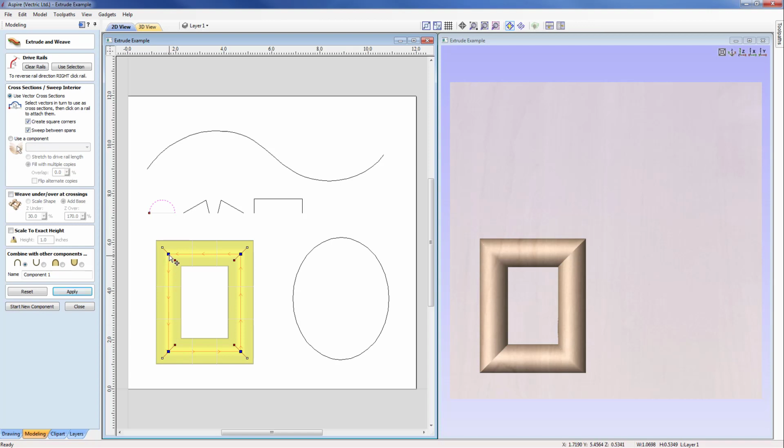So with this, I know that I'm going to have a rounded shape in my top left, a rounded shape in my lower left, and a rounded shape in my lower right. But what I want to do is change my upper right to be this triangular cross section. So with that, I can just pick that up now and then click on the blue node, which will then map that across. We can see the yellow node on the cross section matches the yellow node of the selected cross section, so we know the mapping there. And now I can come across and just apply that to see the change, and even then I can come in and further modify that by essentially moving that cross section down and reapplying.